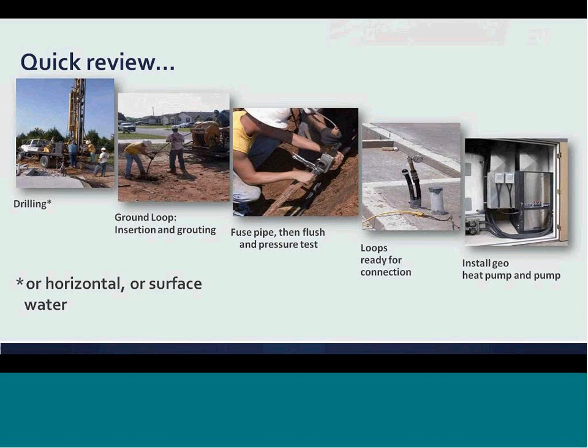This first pressure test is required by IGSHPA, and again IGSHPA stands for the International Ground Source Heat Pump Association, which is the current industry standard. Next, drill the borehole. Insert the pipe into the borehole and grout it from the bottom of the borehole all the way to the top. Notice I've said that 4 or 5 times through the course of this presentation.